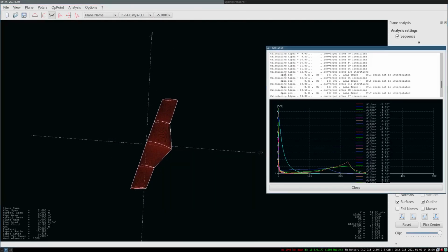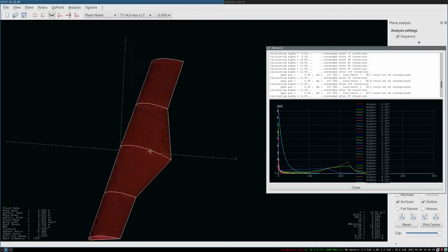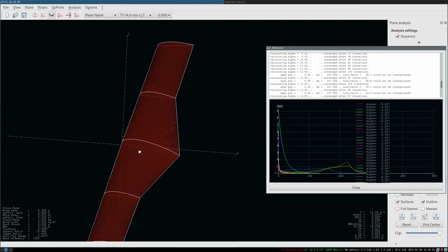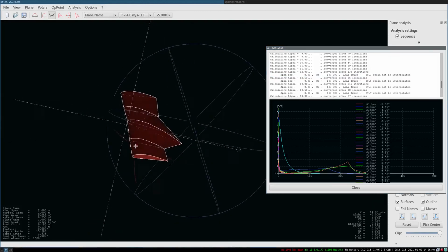is that quite close in? Yep, span past 0. So where we put in the extra 15 degrees of angle of attack when we defined our wing, and we're adding an additional 12-ish degrees plus the relative wind direction, U infinity, I think, as Dr. Green put it, we're actually above the maximum point that we simulated for that Reynolds value on the batch analysis we did earlier. So this is actually where you'd be limiting yourself if you did a very small number of angles of attack.